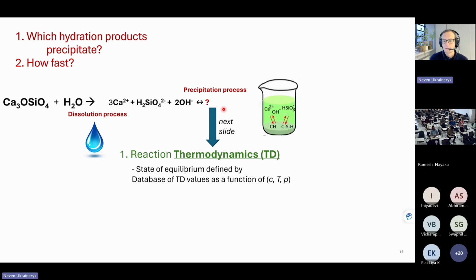So this would be equilibrium. You go back to the original raw materials, which when you burn, you increase the energy, and that's why they react, and then they precipitate portlandite and silica gels. But if you would have CO2, the equilibrium actually would be calcium carbonate.